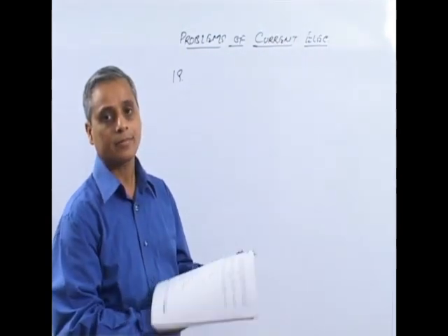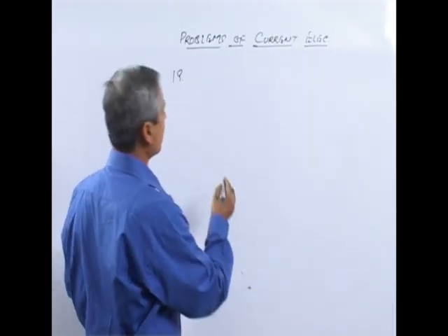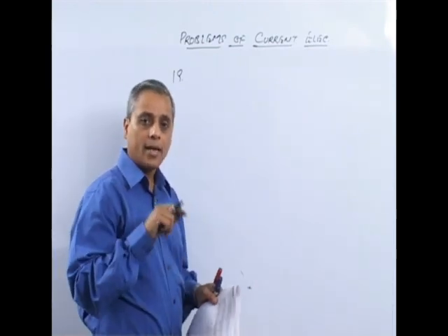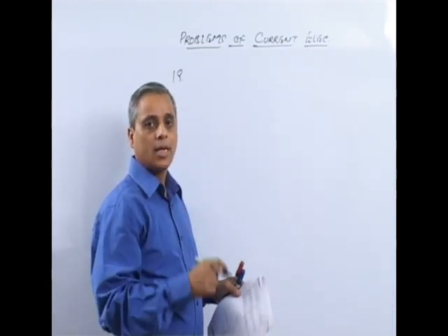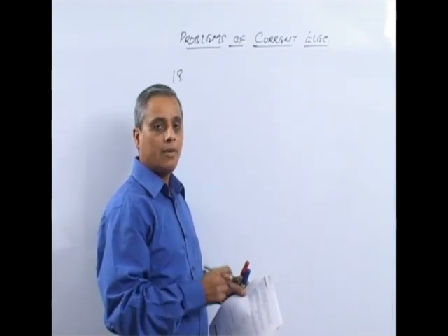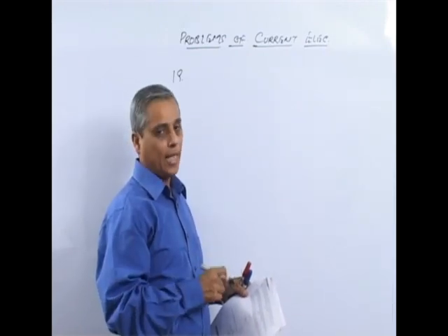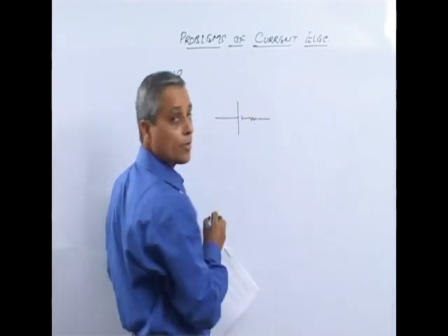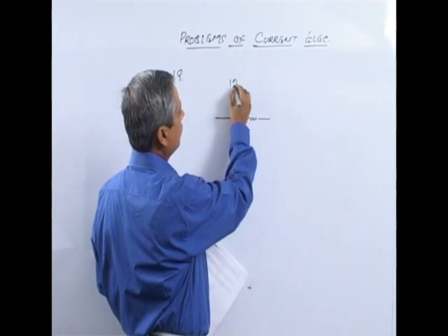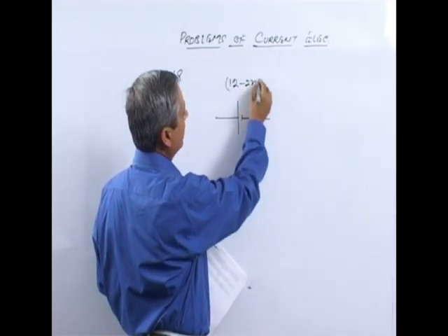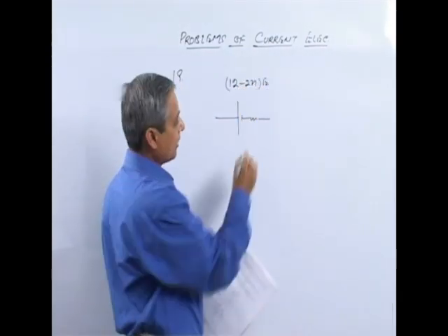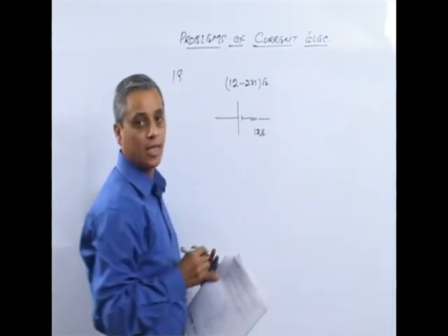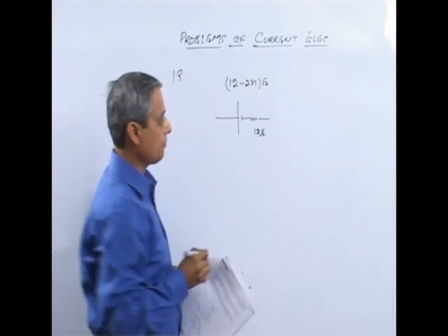Now see, if out of 12 cells you connect n cells wrongly, their EMF is not available. At the same time, they will cancel out the EMF of n more cells. Therefore, you will have a battery whose EMF will become (12 minus 2n) times E, but resistance will remain, of course, 12 r, if r is the internal resistance of each cell.